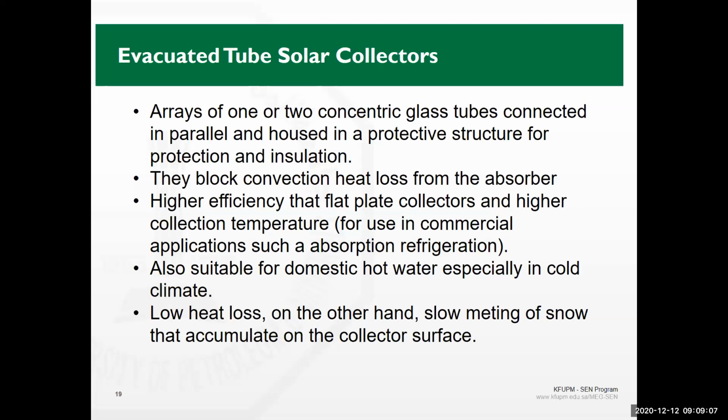The problem with evacuated tube collectors is if you are using them in very cold climates where snow is falling, the collectors are not transferring energy outside. So the surface of the collector remains cold. So if you have ice accumulation on the collector, you cannot get rid of it easily.